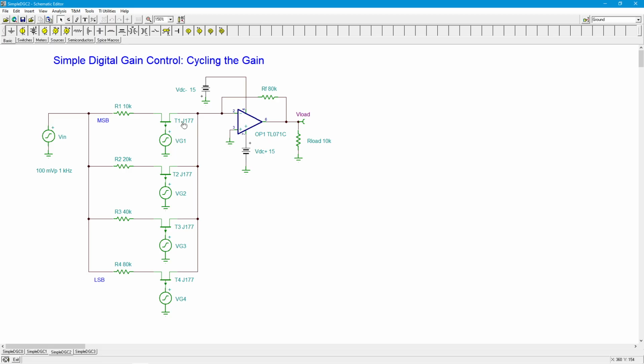All depends on how fast you really need to switch, but that is what would feed the gate of the FET. So you would run the port bit, right? So imagine that's coming in over here. So you'd have resistor in, cap going down to ground. So that slows up the edges, and that's going to clean up things.